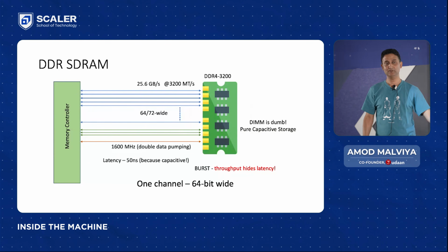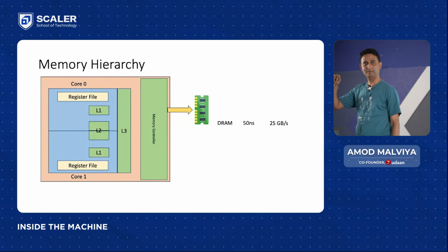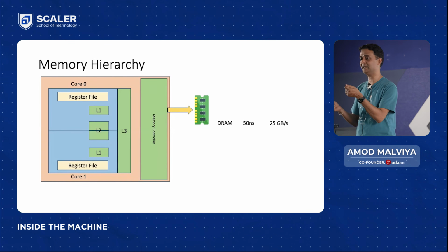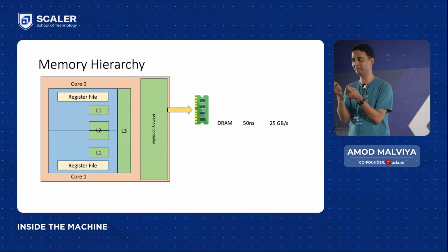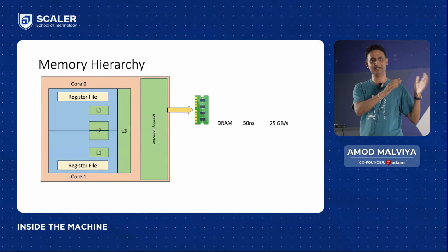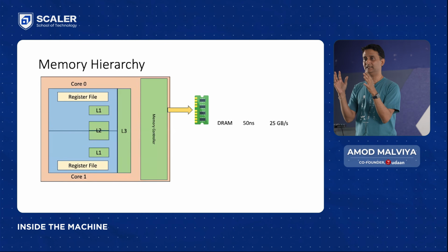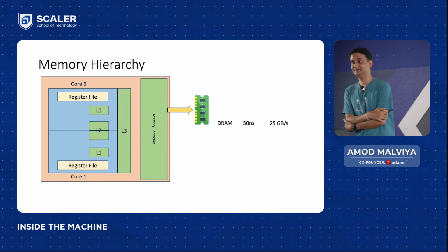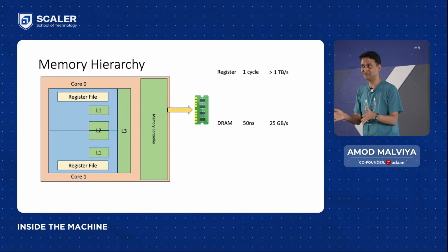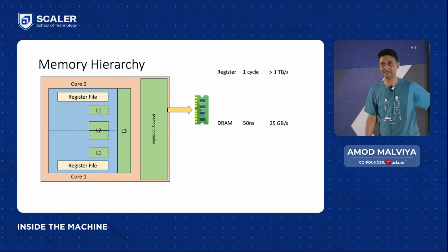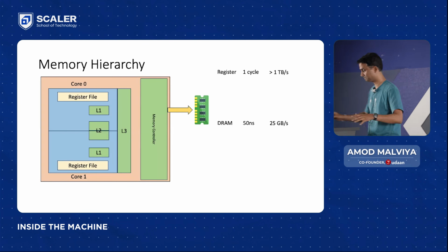So these SRAM, going back to the flip-flop, uses 6 transistors. DRAM uses 1 transistor, 1 capacitor for 1 bit. We call it 1T, 1C. SRAMs are called 6T. There are better circuits also sometimes, but 6T. That's the reason why it's expensive. For the same physical size, you can store much less in the case of SRAM.